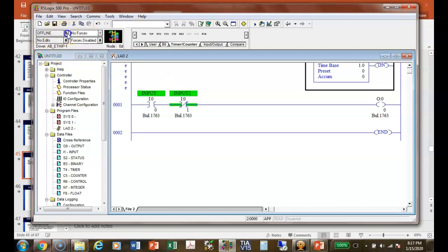So I'd come right here, and I'd click download. When I download it, what's it going to do? It's going to translate it. And what this guy does, it doesn't see the high-level language. It sees the binary program after it's been translated. So the binary program goes to the network cable, comes over here, and it stores it in the memory of the PLC.